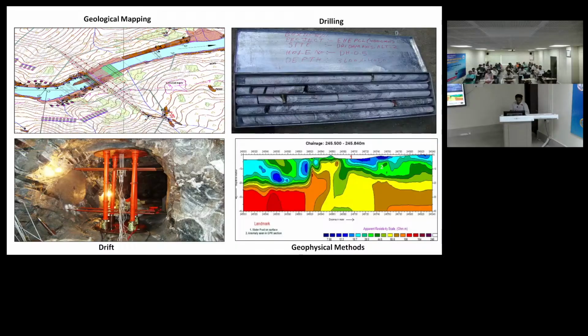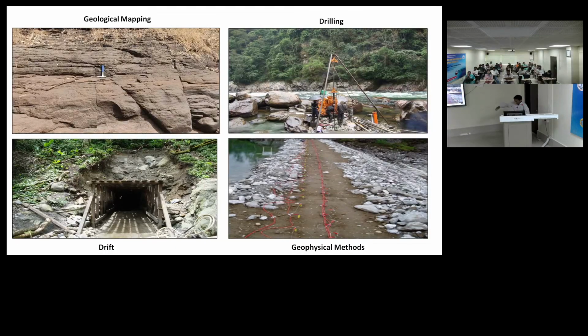Always recommended is to do some bores, drillings, and if the problem is severe, you also do geophysical. Compare these two, because like I told, drilling we will do at different locations only, so it gives only point data, but geophysical can cover the whole area. You have done one drill hole here, but some particular information is missing here, so to get that information and to save time, we can do geophysical and drilling and compare both results. So clear? We will be doing these 4 investigations, and results will look like this.